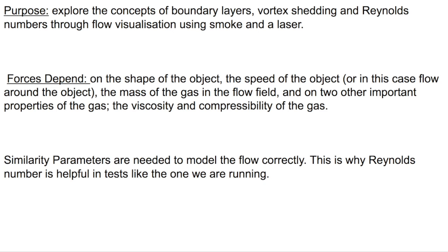To properly model these effects, aerodynamicists use similarity parameters, which are ratios of these effects to other forces present in the problem. If two experiments have the same values for the similarity parameters, then the relative importance of the forces is being correctly modeled. This is where Reynolds number becomes very applicable for the aerodynamic world. A comparison between the density, velocity of the flow, length of the test section, and dynamic viscosity can allow scaled model tests in wind tunnels to occur, since the dimensionless Reynolds number of the model can be applied to a full-scale scenario.